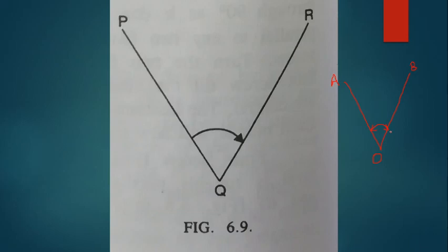Theoretically, in this method the angle is added a number of times and the total angle is divided by the number of readings to get the accurate horizontal angle. That is the main principle.